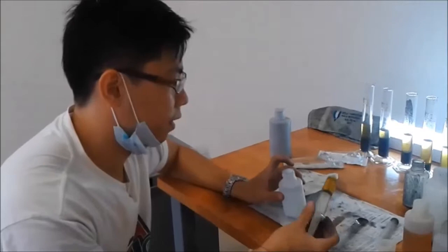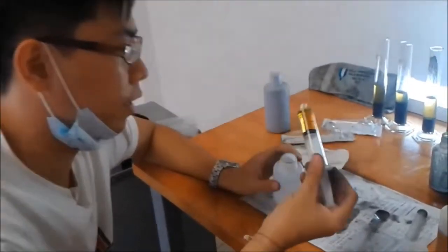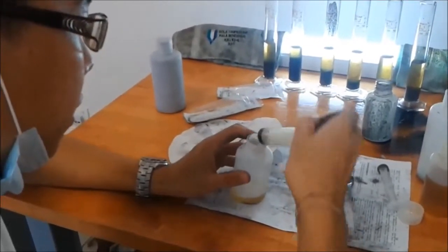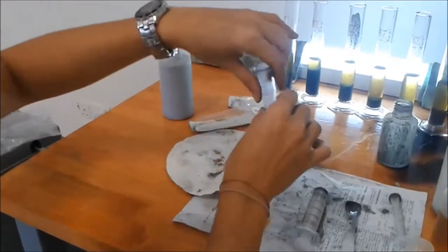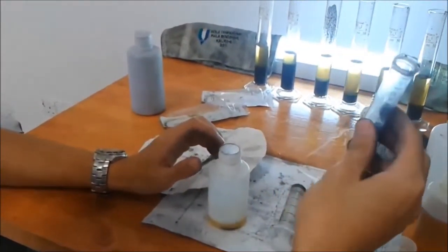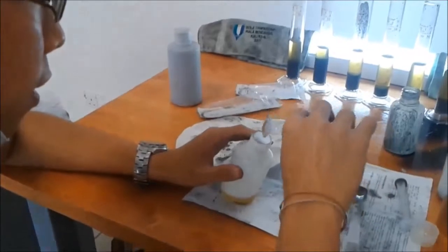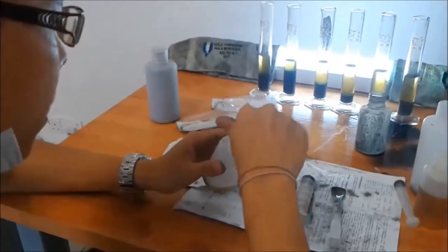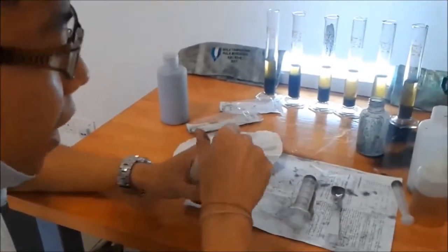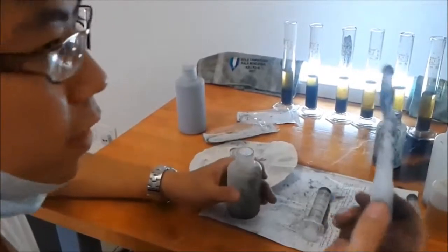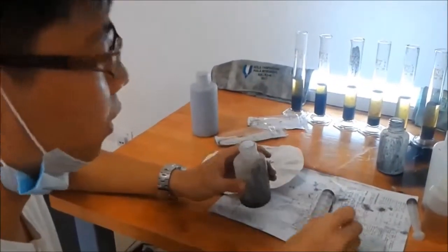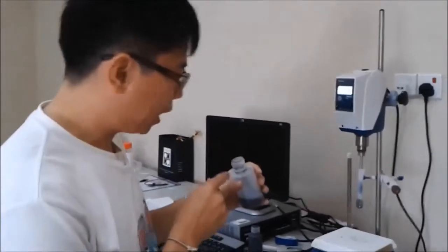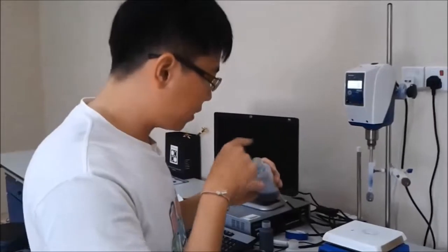For the experiment, first I will put the carrier fluid, this is the carrier fluid, Caltex hydraulic oil 32, inside the container. Then I will put the carbonyl iron, CI particle, CI powder, magnetic particle into the container. So I will mix it and go to the stirrer machine to stir it uniformly. I would like to use a stirrer machine to stir the MR fluid, magnetorheological fluid, to make it